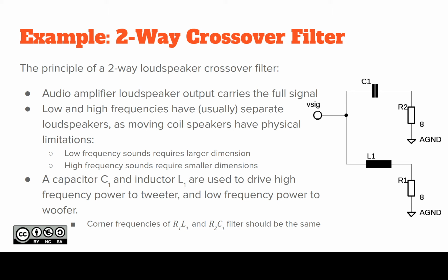Why we are doing this is to separate, inside of the loudspeaker box, the signal which goes to the higher frequency speaker and the signal which goes to the lower frequency speaker. And now the signal is coming in basically as a wire pair. So there's a ground reference and the signal. Okay, so this signal has the whole spectrum when it gets out of the amplifier itself. So you need to do the separation inside of this loudspeaker box.